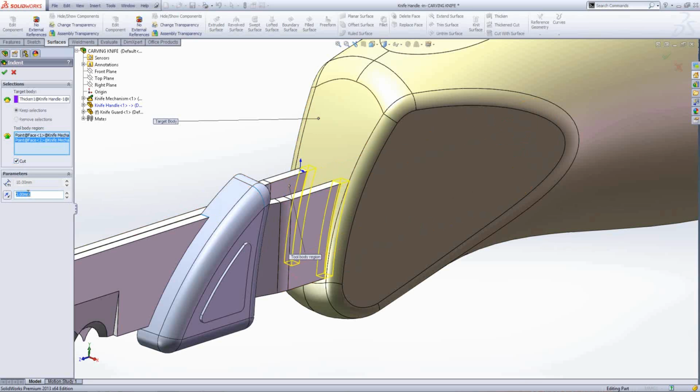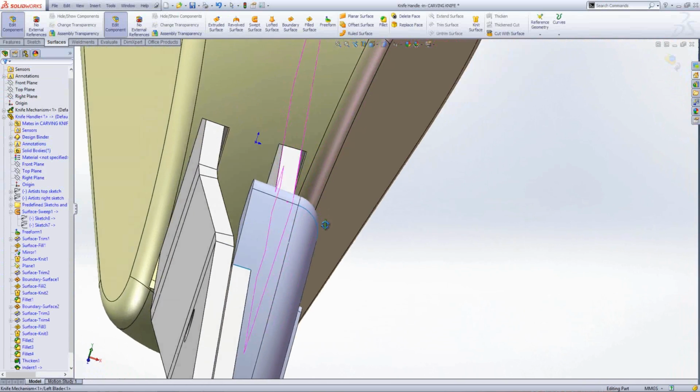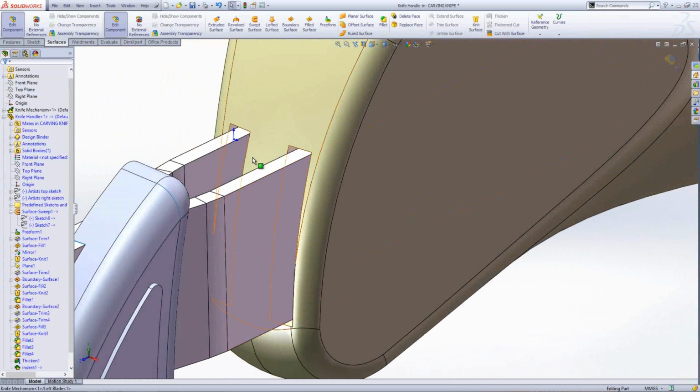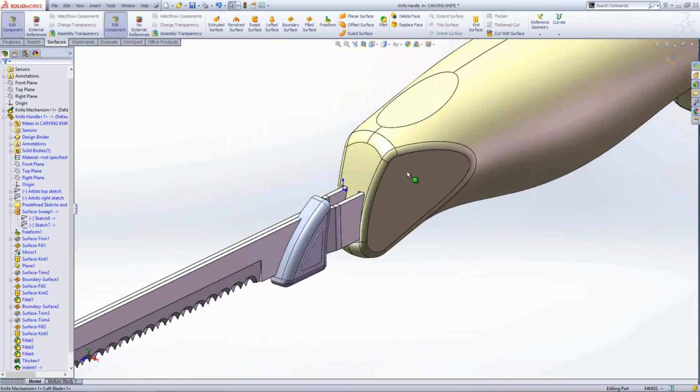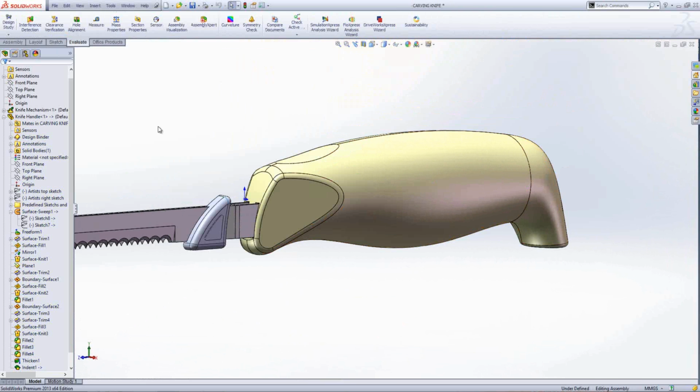And we can specify an offset size within here, so maybe we put a 0.5 offset around those just to give it a little bit of clearance. Just click the OK button and you'll see there that we create those two cutouts just to allow those blades to move. Okay, so that's worked really well. So we're sort of done now in terms of error checking.